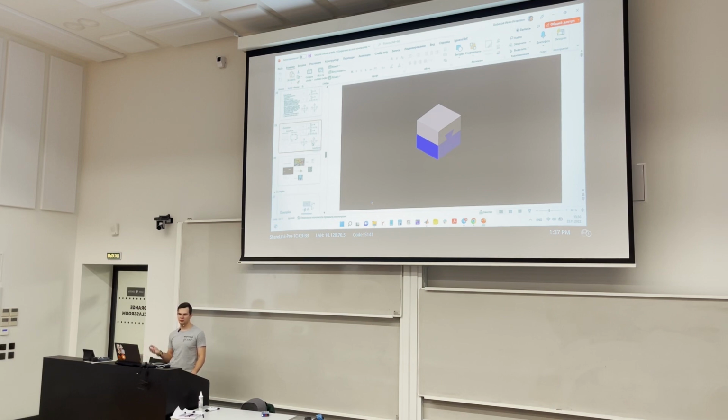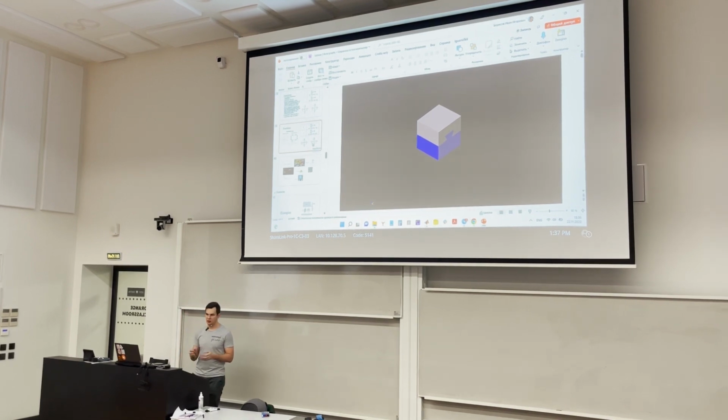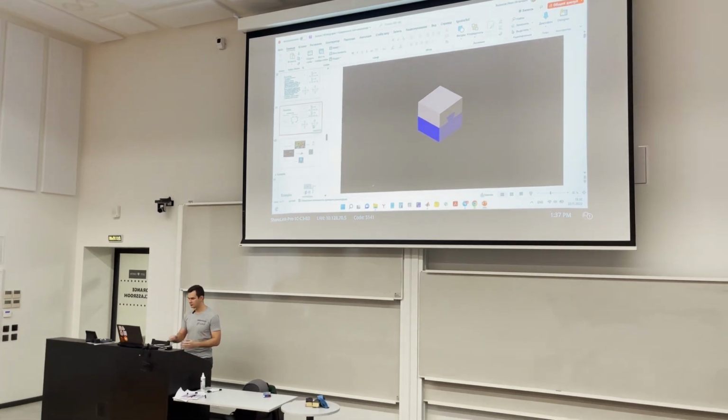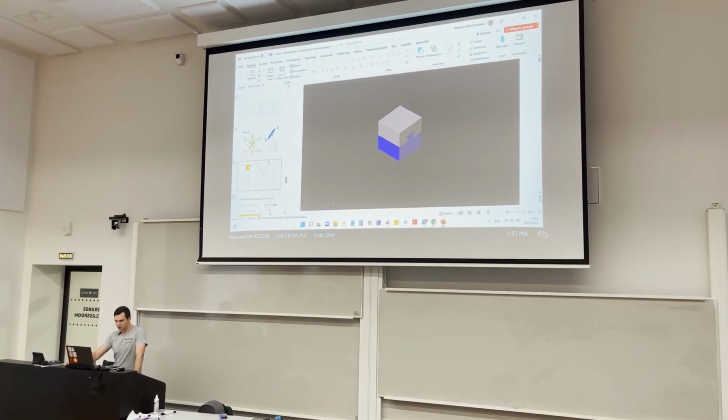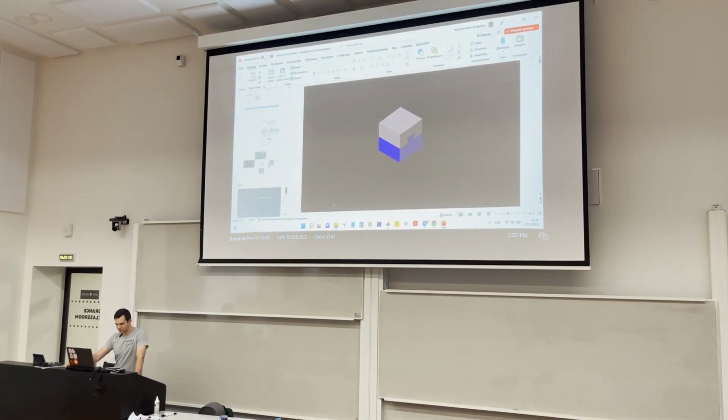But basically what you have to do is to derive an Euler-Lagrange equation symbolically. Then you need to create a simulation model using basic Simulink blocks, and then do the same using Simscape blocks. And the results must be the same. If the results are the same, it means that you have done everything correctly. Okay, it's like a small recap of the first and the second lectures.